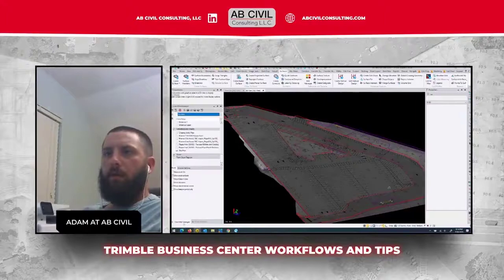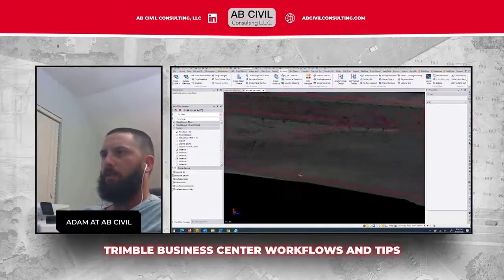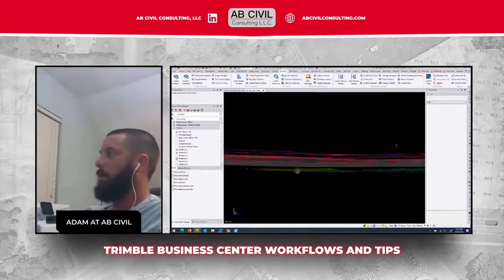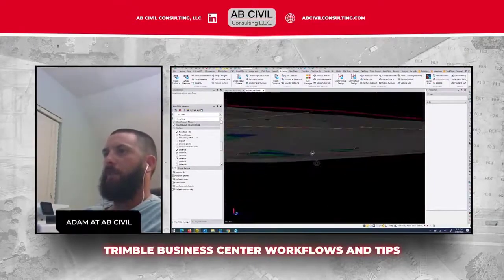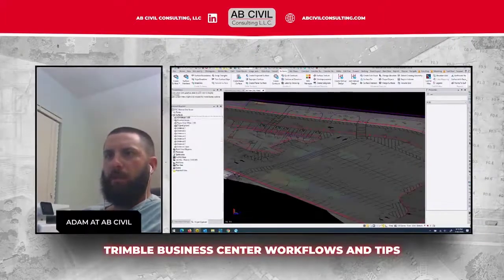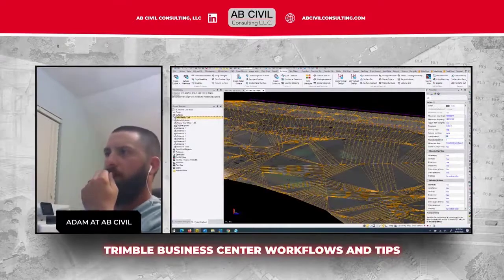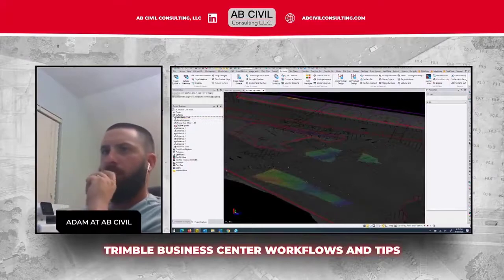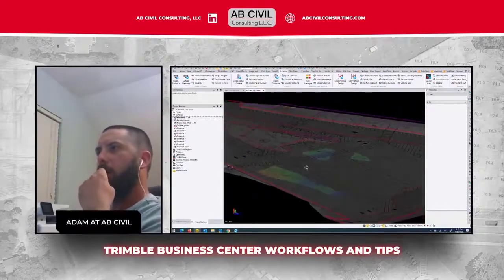Alright, so now I've made my surfaces. So you can see these surfaces are below the offset surface. And that's representing the extra, it's all the undercut that they did. This was just a straight topo on the bottom of everything. So I can adjust the transparency too. It's at 20 right now, but I probably want to kick it up to at least 50. It might be a little too much. Almost looks like those surfaces are right on top. Yeah, that's pretty good. 40% transparency on the offset surface.